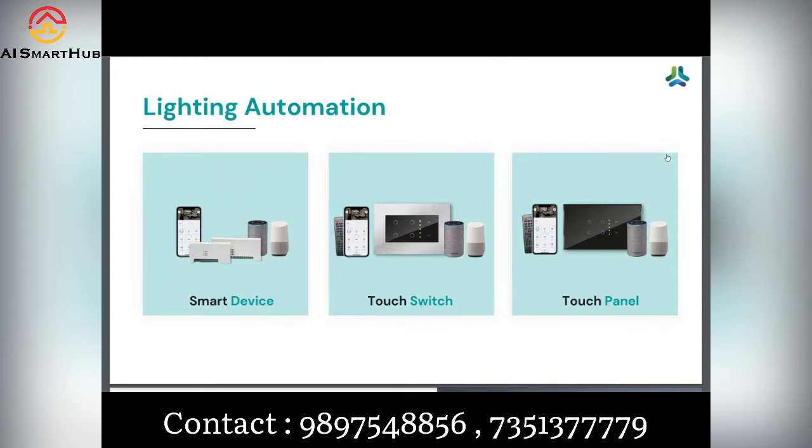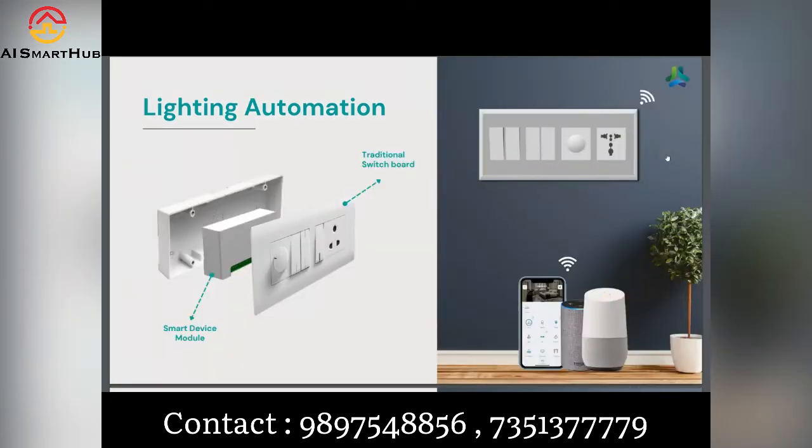We have classified lighting automation into three main categories. One is smart device, second is touch switch and third is touch panel. The client who wishes to automate their house with the traditional switch can go for the smart device. The smart device consists of only a backend module that fits behind your existing switchboards and works directly with your traditional switch. The smart device will automate all the loads in the switchboard. Any traditional switch can be converted with smart devices.